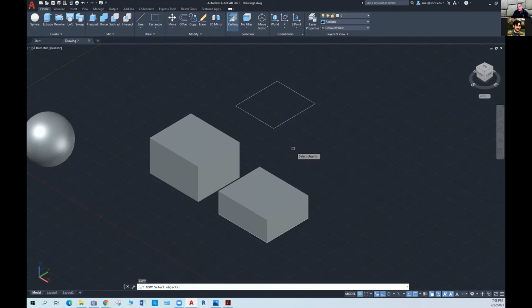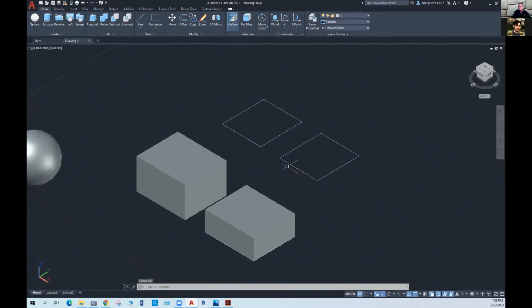If the line segments are not joined, for example, an exploded polyline, then the resultant 3D object is going to be a planar extrusion surface or a face, right? So those are different things, different ways to create geometry. And remember that you can use any profile to create geometry, right? That's the idea in AutoCAD.